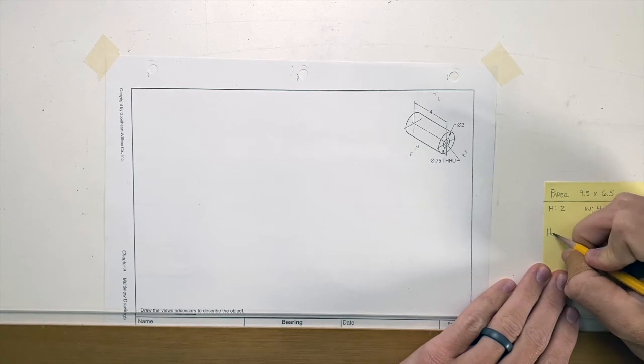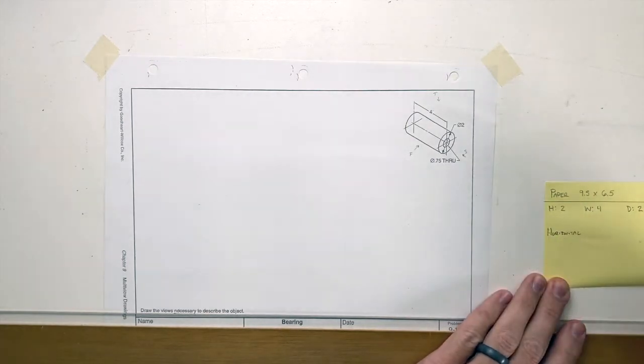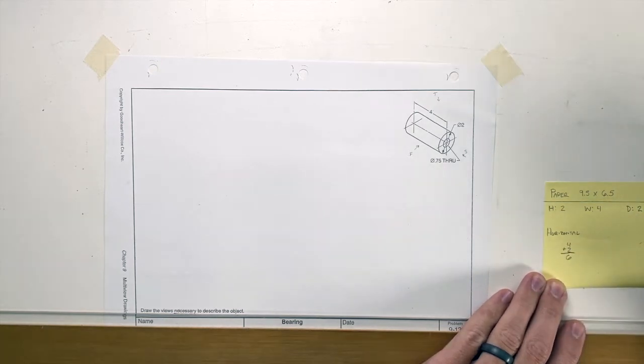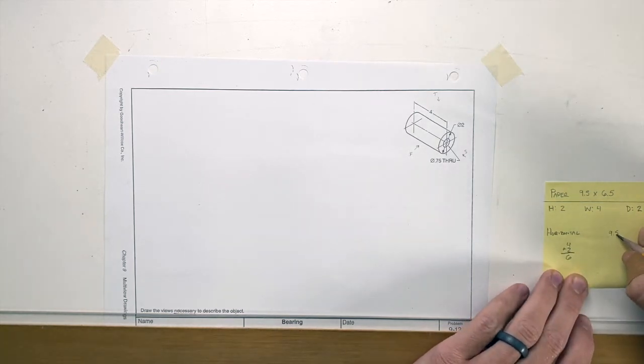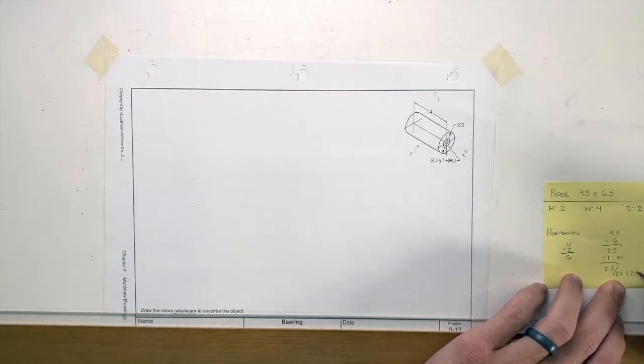So for the horizontal spacing, we are dealing with 9.5 inches to draw within. I just said we have 4 plus 2, that equals 6. If we take the 9.5 and subtract the 6, we have 3.5. We've been making that middle space 1 inch, so I'm going to subtract that 1 inch, call that middle space. We are left with 2.5 for either end. So we are going to divide that by 2, and that equals 1.25 for our other spaces. We'll just call that S.